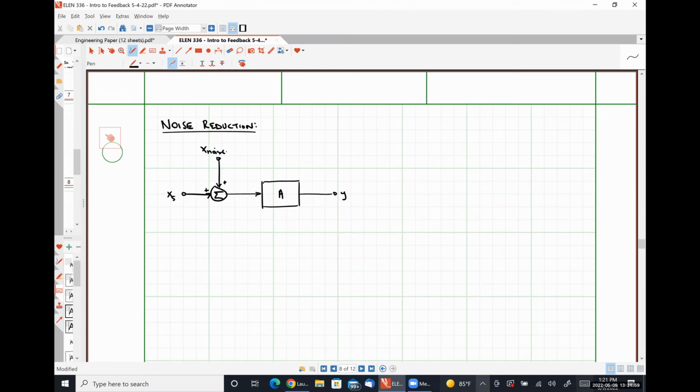All input referred noise means is that if I have a very noisy amplifier, like what you ladies experienced in the lab the other day, you see the noise at the output of the system. Well, the input referred noise is simply that noise at the output divided by the gain.